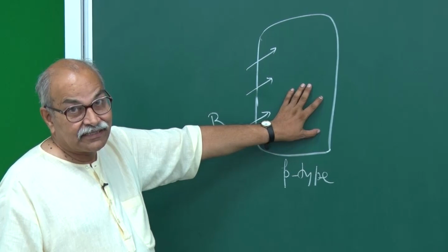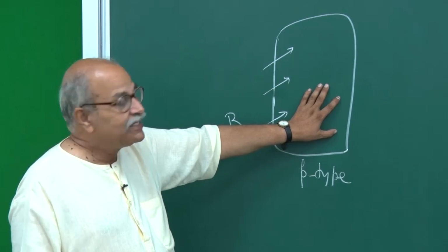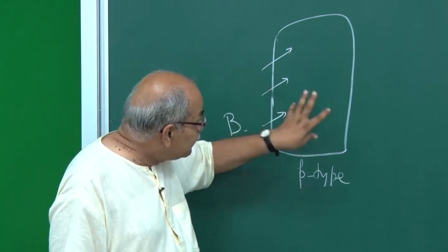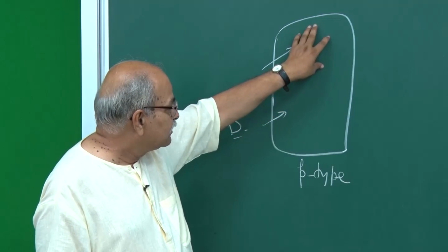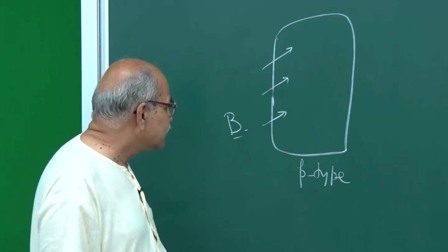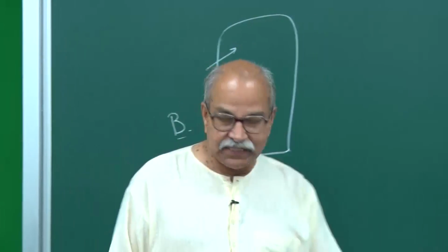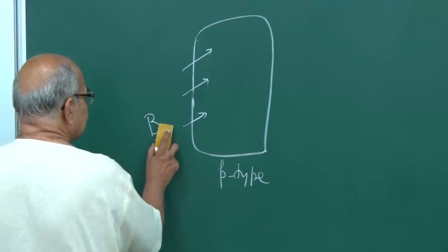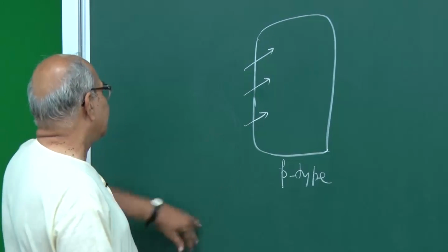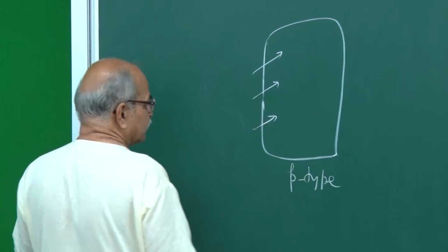Silicon I am taking as our model semiconductor. In any kind of semiconductor you have to do all this processing, and so through very controlled processes without finally disturbing that crystal structure, you have to put these impurities at those lattice sites. So, this whole thing becomes p-type, and once this whole thing becomes p-type, after that you, in a very controlled fashion, diffuse n-type, and for that some pentavalent impurities like arsenic or antimony.